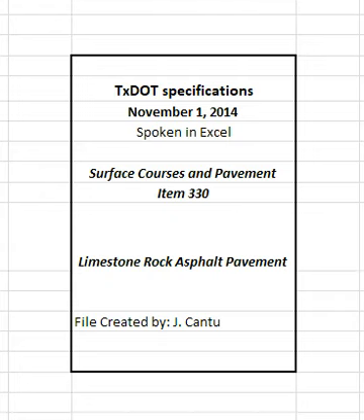Prepare the surface by removing raised pavement markers and objectionable materials such as moisture, dirt, sand, leaves, and other loose impediments from the surface before placing mixture. Remove vegetation from pavement edges. Place the mixture to meet the typical section requirements and produce a smooth, finished surface with a uniform appearance and texture. Offset longitudinal joints of successive courses of mixture by at least 6 inches. Place mixture so longitudinal joints on the surface course coincide with lane lines, or as directed. Ensure that all finished surfaces will drain properly.